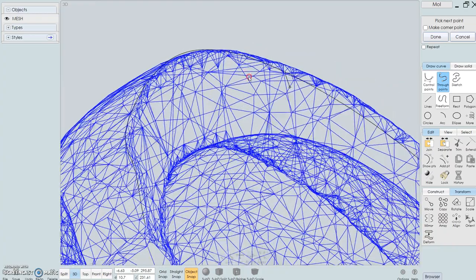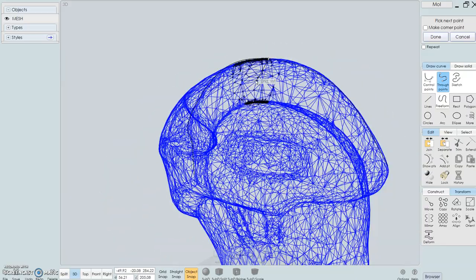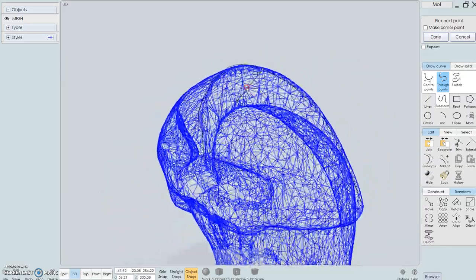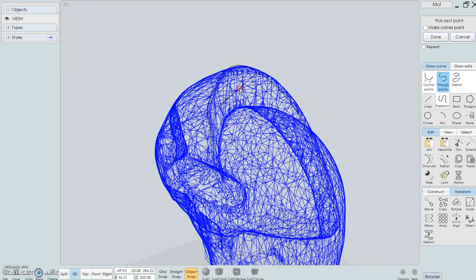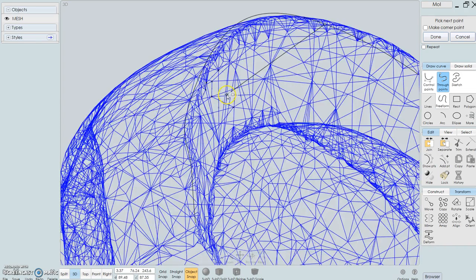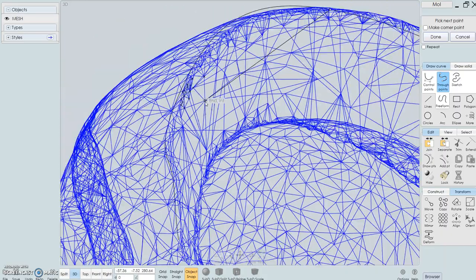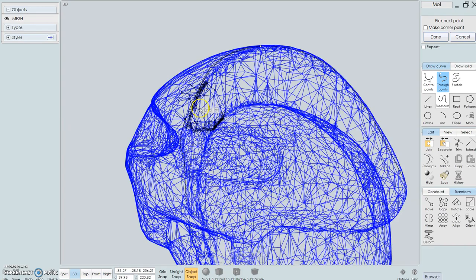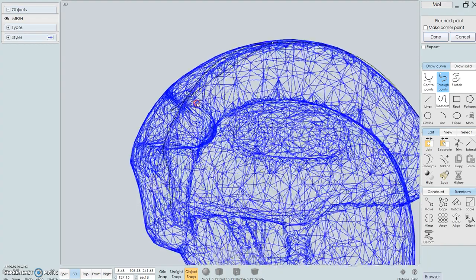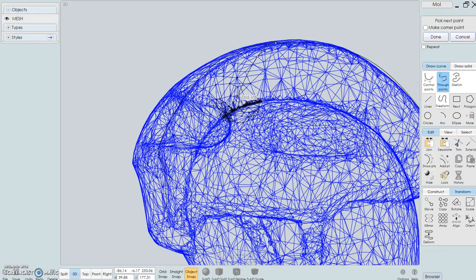And we're going to trace the path on the mesh, but it's a little bit difficult to see what's the surface and what's below it. So by moving it around, I can detect what the next point would be. I can see the point there. I'm just going to get closer now that I can see it, and I'm going to snap it to this point. I'm going to keep finding the next point around. Let's make sure that it is on the top surface. So we're going to pick this one over here.